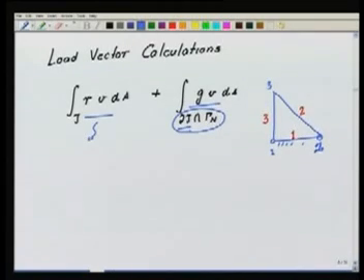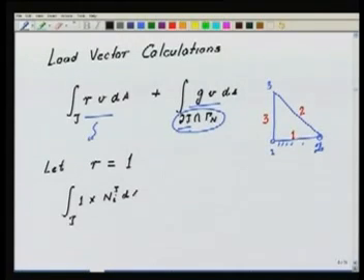Let's say that R is equal to 1. Let's take a constant value of R, and we have taken R equal to 1. So at the element level again, which of the v's are non-zero? It is essentially the n1, n2, n3 of the element. So I'll have to do the integral over the element tau of 1 into ni dA. But this is equivalent to doing the integral over the master element A hat of 1 into ni hat into Jacobian into dA hat.